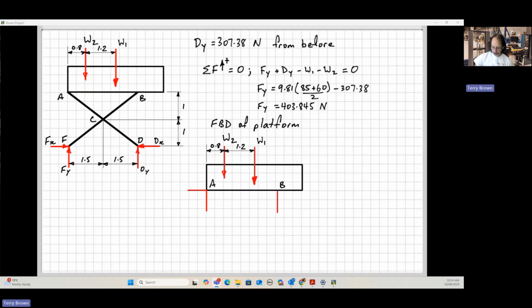Right? So go back and look at the question to see that. I'm not going to flick back. All right, so that's our free body diagram. So now just put on that extra dimension there. Look at the sense of these forces. So if we imagine that we take moments about point A here, these two forces are acting downwards to cause a clockwise moment. This one needs to cause an anticlockwise moment for it to be in equilibrium. So that's why that one's acting upwards.